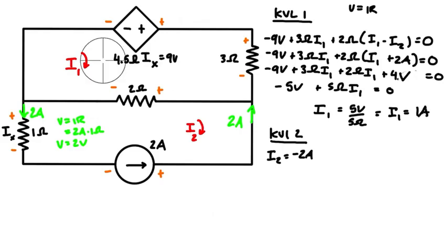So that's basically saying that the current flowing around this part is equal to 1 amp. So we can label that coming into this junction here as 1 amp, coming out of this junction as 1 amp. And you can look at this side, if we have 1 coming in and 2 coming in, there has to be 3 going out. So we have 3 amps, and then same here, we have 3 amps coming in and 3 amps going out.